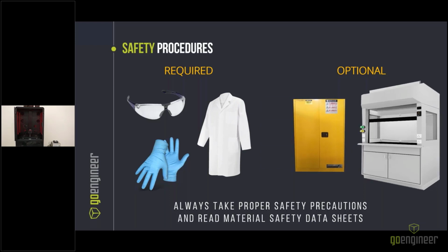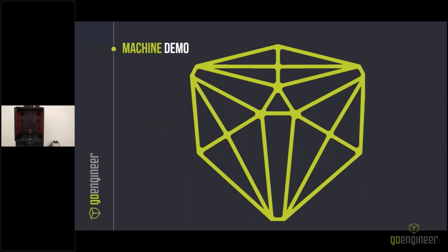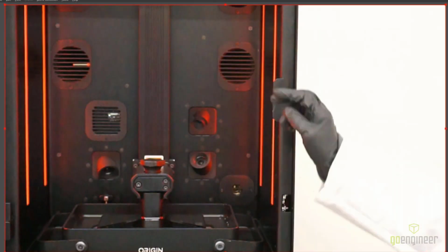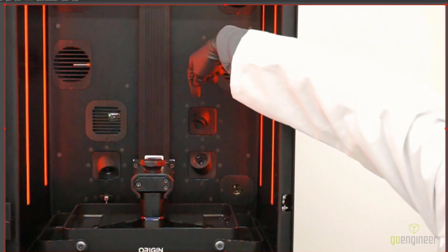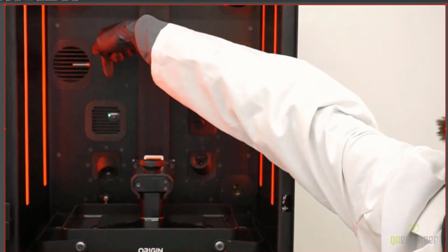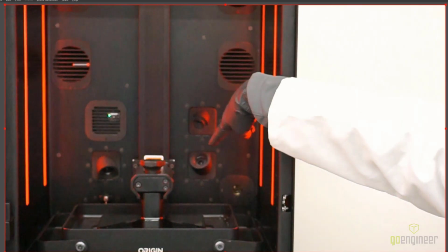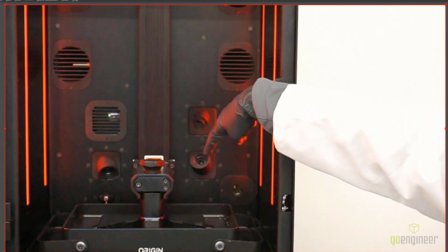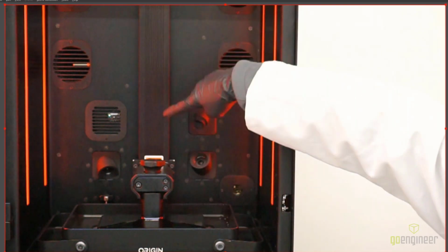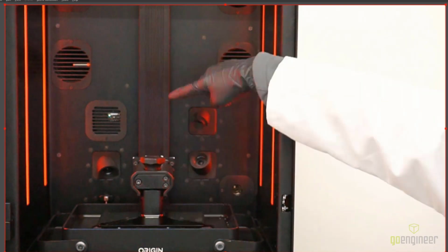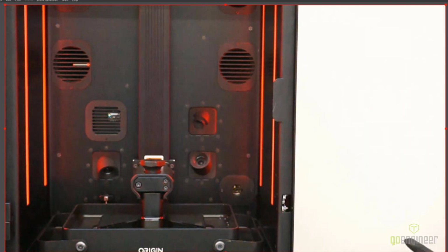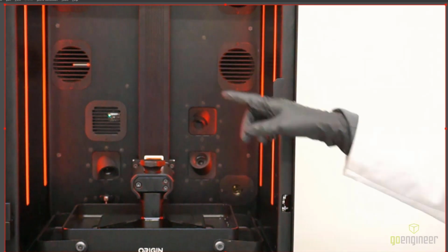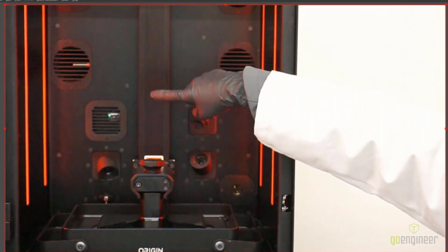And with that, I would like to actually jump a little bit more in depth to the machine itself. So up top here is one of the IRs. We have another IR on the left and a regular camera directly below. There's only one moving component on this machine, and that is the Z stage. This makes maintenance extremely easy and simple. You have a couple fan filters that need to be replaced and lubricant on the Z stage once yearly.